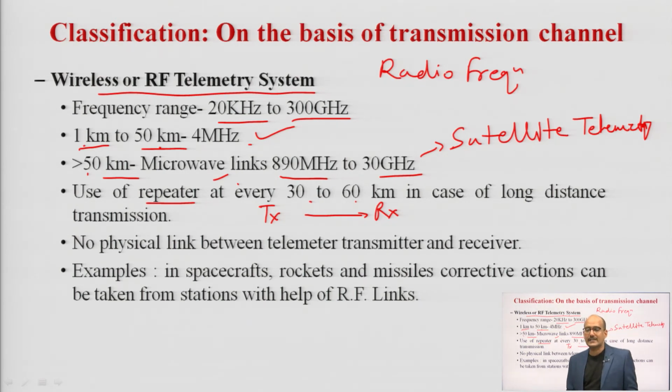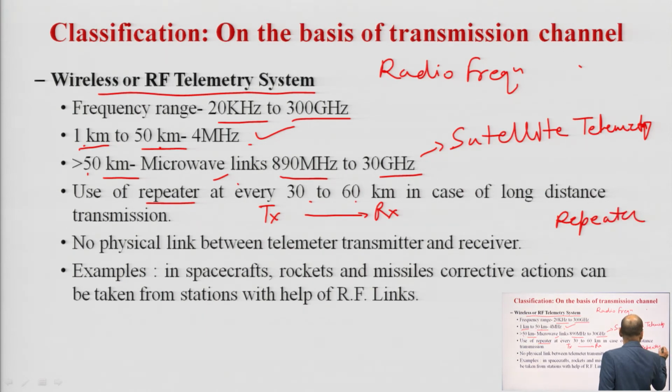These repeater circuits receive the data. The received signal is filtered, meaning the noise is filtered out. After that, the signal is amplified again and then sent on towards the receiving end. So at the repeater, you perform filter plus amplification.